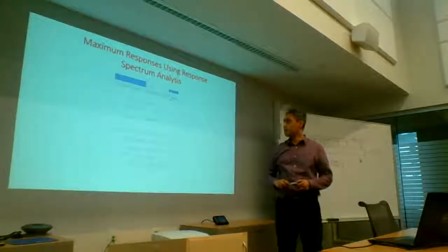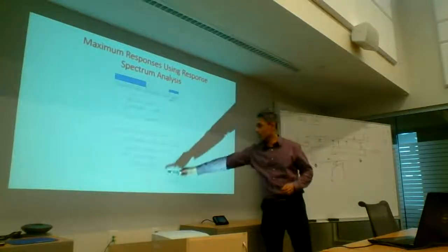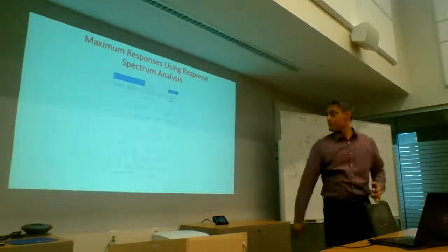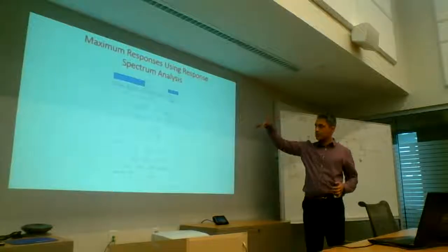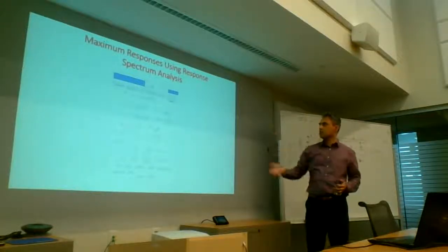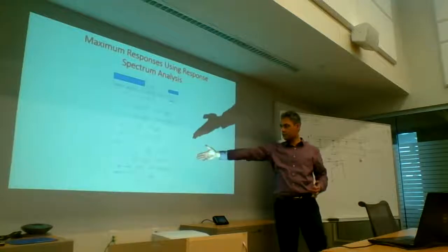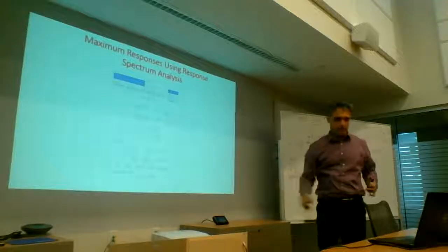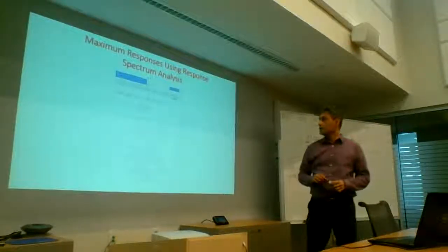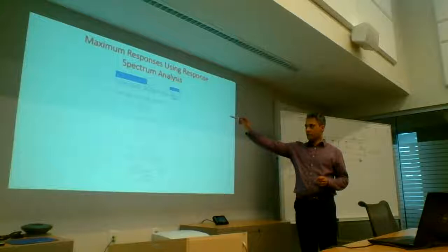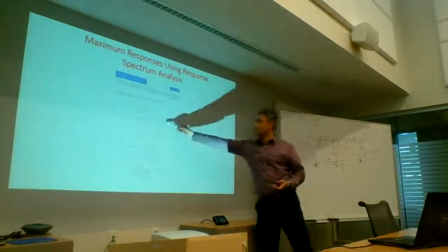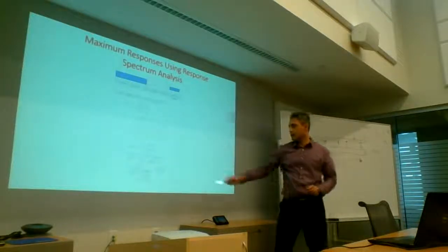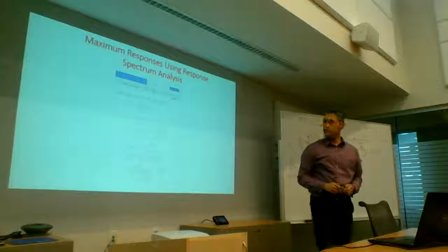Just to simplify, I say lambda is omega squared. So you end up with this quadratic equation, because we know we're going to get 2 roots out of it, right? And then you get the lambdas that are the square of the omegas. You take the square root, you get the omegas, you get the T's, and then we calculated the mode shapes earlier, so they're right there. Now we calculate the modal participation factor, and now you see that this one helps you. The transpose times this times that, and it comes out to be 1.1708.